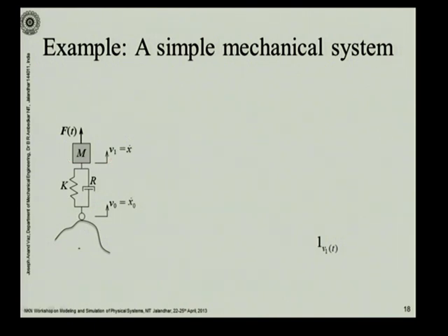I am just considering motion along one dimension only, and so we have a one junction here representing the velocity v1, and it may change with time. Then we connect it to an I element. Why? Because this mass is going to move with this velocity. So directly we place this mass on this one junction.